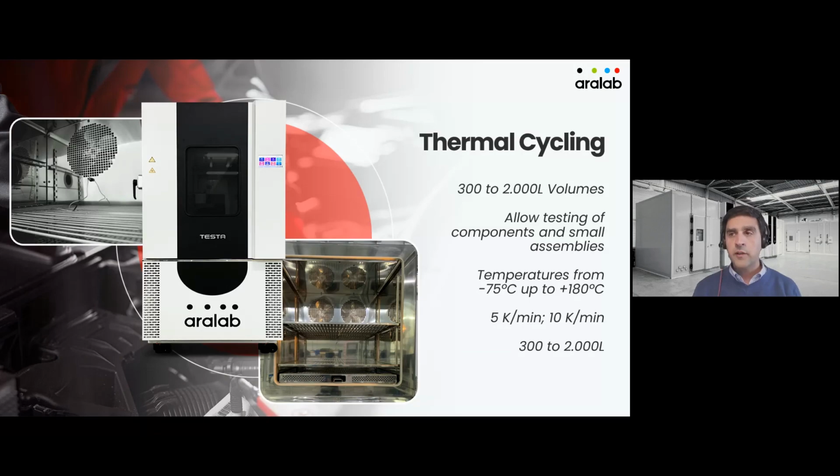So a very common case is the GPS or the radios in our cars. They're individually tested, but when they are applied to the dashboard, they start to have interactions with other components, and there may be localized hotspots where temperature spikes, and so they have to be addressed. Okay. And by the way, we do this in a climatic chamber. And then in the end, for example, the whole dashboard may go to a vibration chamber where the whole thing is shaken, so that we make sure that in everyday life it's sturdy enough.